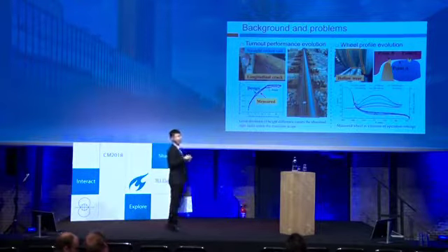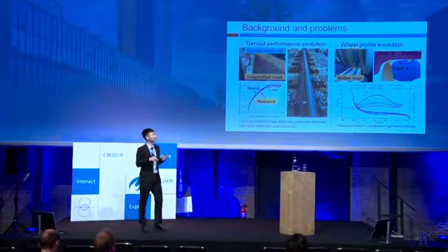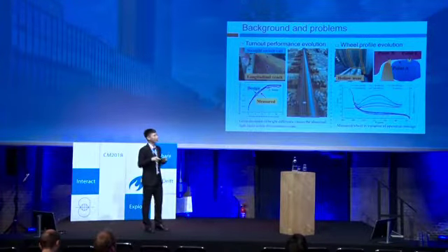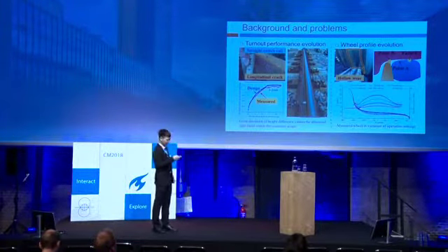In detail, when the hollow wear is formed, the curvature at the hollow bottom of the wheel is smaller than that on the rail head, so the contact position may shift laterally to the contact point B or C, instead of point A. So considering the multi-point contact in the turnout and the varied cross sections, the wheel-rail relationship may get more complicated.